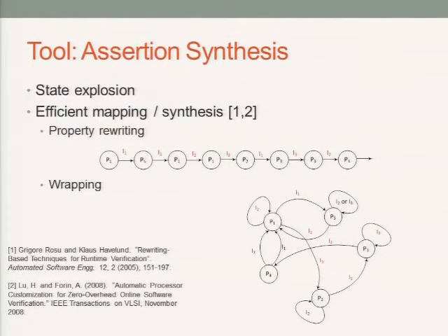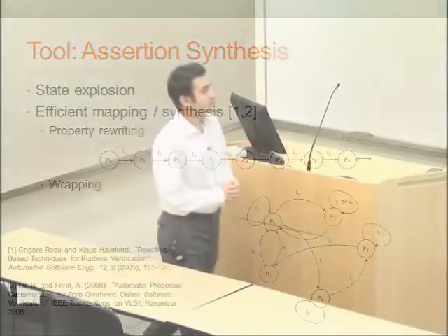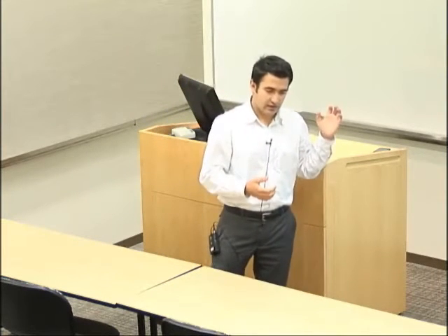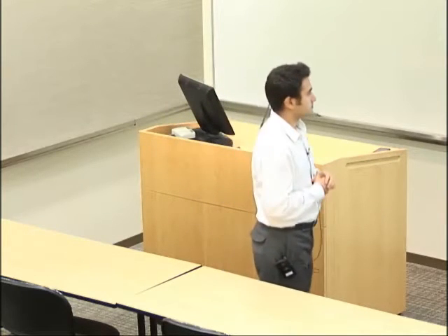Okay, now after you get these assertions, you have to map them, synthesize them to a state machine. So this is still a challenging problem because you might end up in a state explosion. So you want to efficiently map this logic statement into a state machine with a minimal number of states because you don't want to use a lot of hardware. So in a paper in